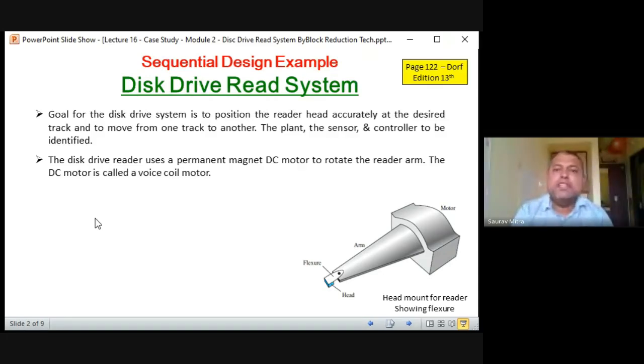First thing, there is produced a current by whatever electricity we are giving to the motor. First input. Second input is there is a coil. So we know how to produce an electromagnet. There is a winding and there is a ferromagnetic material. If we are supplying current through that coil, then an electromagnet is produced. Whenever an electromagnet is produced, flux lines are produced. So if there is a flux line and a current carrying conductor, and there is a relative motion between them, then a force is produced.